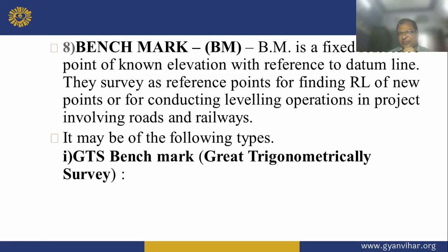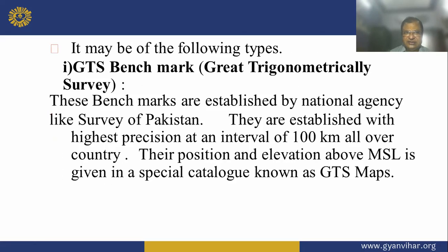And finally, the benchmark. A benchmark is a fixed reference point of known elevation with reference to the datum line in a survey, used as a reference point for finding the RL of new points when conducting leveling operations in projects involving roads and railways. It may be of the following types: GTS benchmark, which is established by the Great Trigonometrical Survey.